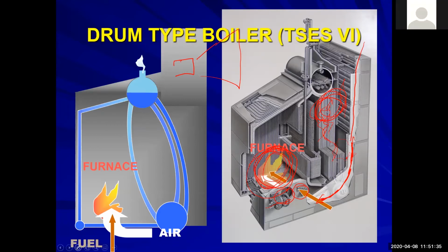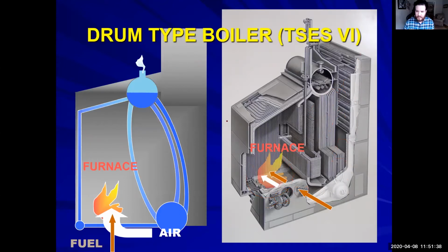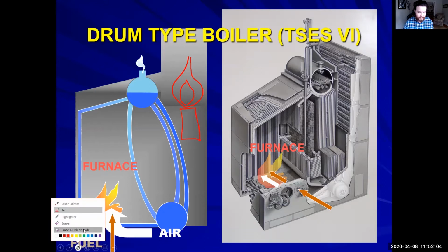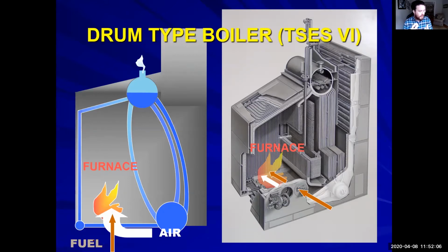Are they an oxidized flame? What do you mean by that? As in like a hot blue flame compared to like... Oh no, you're not going to have a burner tip that looks like, where it's an inside or outside flame like if you had a Bunsen burner. Okay, these are going to be dirty. They're going to have red. It's going to be a deep amber color.